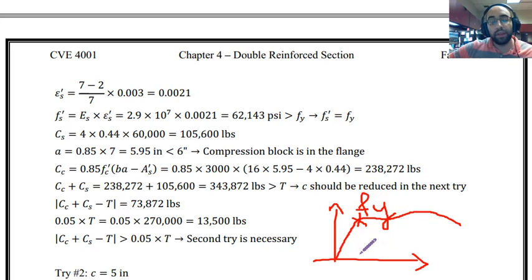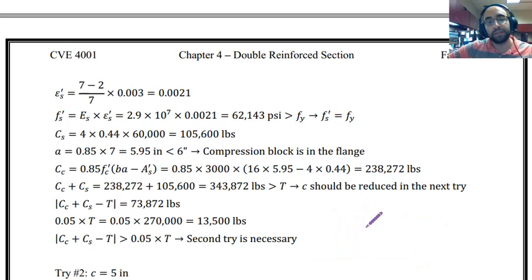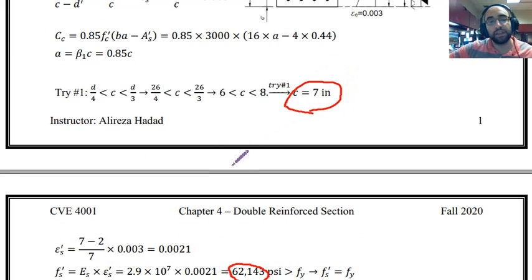As you can see, in the domain of regular loading and ultimate strength of the section, it just reaches Fy and it does not go beyond Fy until the failure and very extreme loads. But for regular design, we always assume Fy is the maximum stress, and beyond that is just failure and yielding. So as you can see, a stress in steel cannot go beyond Fy. That's why when you calculate this stress in steel based on what you assumed as C, we assumed C is 7 inches.